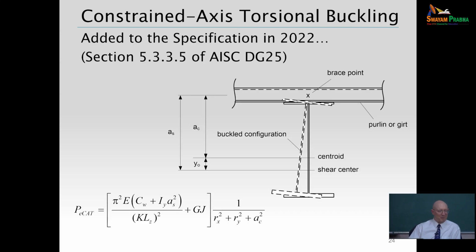It's very common for many of the manufacturers to design the frame as if every purlin and every girt location is braced, unless there's a door or something they know is not going to be there. And then they come back and do a calculation, okay, which of these diagonals do we really not need? And they'll remove those from the design.